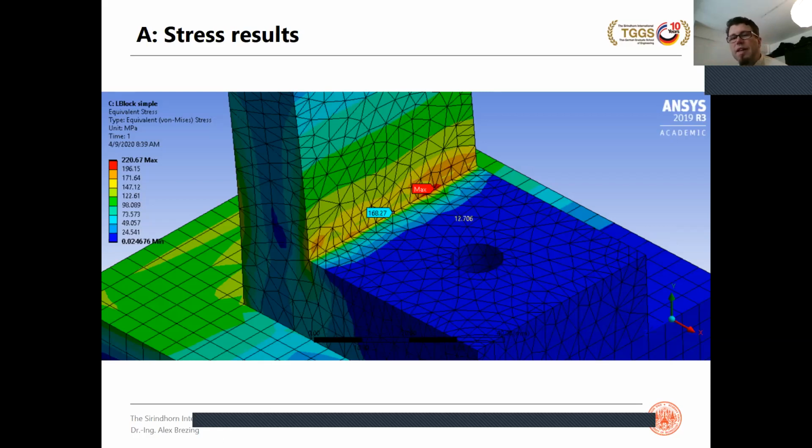On principle, this is a two-dimensional load case, right? So on principle, you should have the same stress level all along the length of this edge, but the simulation is pretty different. You have, I would say, variation, just roughly guessing, from mid-yellow, that would be 160 to 220, which is quite a lot of variation. So that is also an indicator that we shouldn't be trusting the numerical result as an exact result. Never ever, especially with this rather coarse mesh.